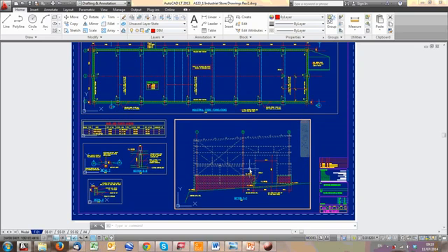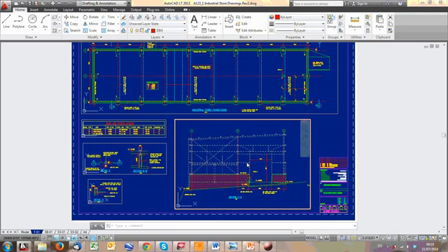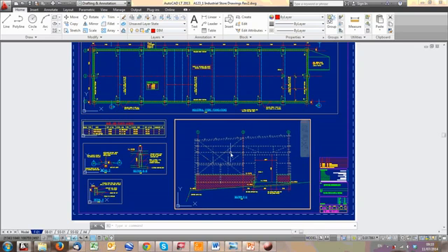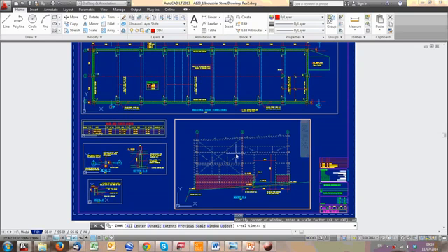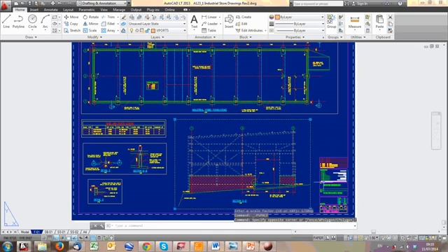If I want to create a specific view, a specific scale, and I'm going to do this again because everyone always confuses this, I'll do this in future lessons. If I zoom in, I want to create a 1 in 50 scale now. I zoom out, zoom in. I get roughly the section where I want it to be. Now I type Z, zoom, enter, S, scale, enter, 1/50 XP, enter, and it will create a scale for me. I'm going to lock this up.